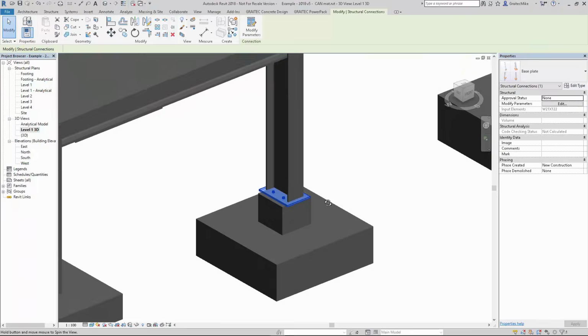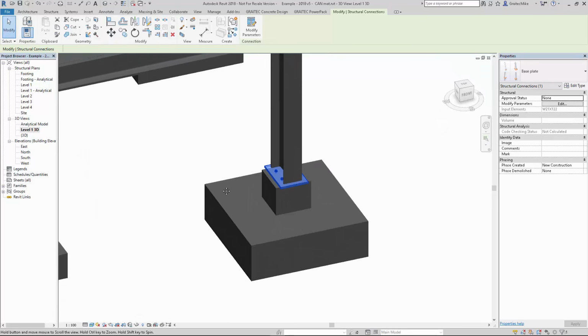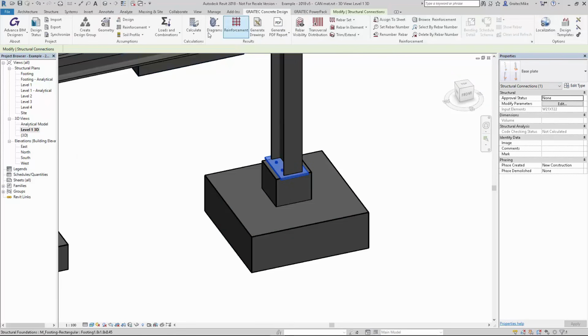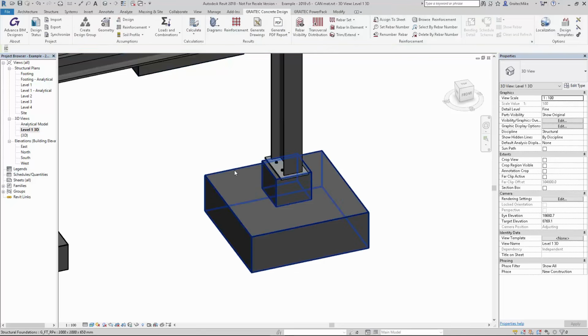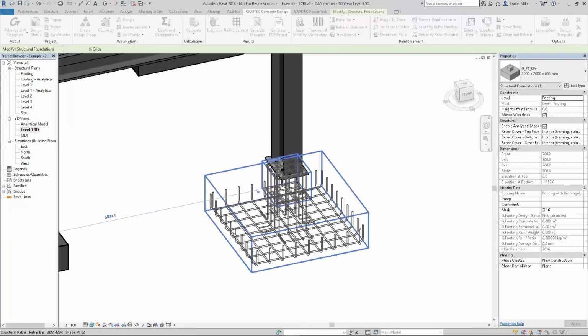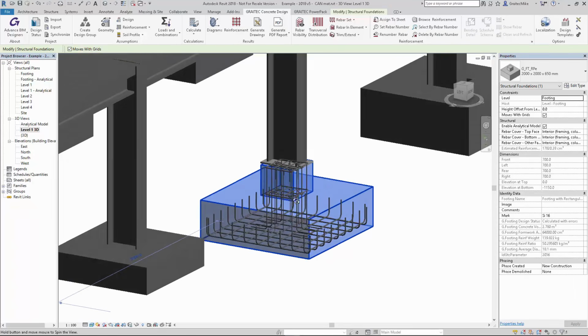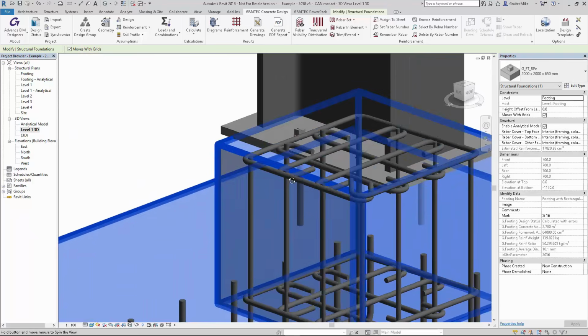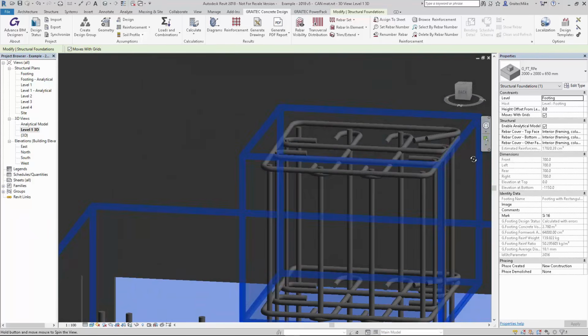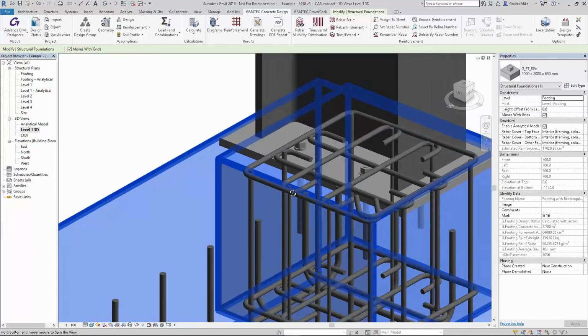Once we launch our calculation for our concrete element, we'll be able to see the rebar in 3D. This will give us a view and ensure we could verify if there is a conflict between several elements. So we're launching the calculation here. We're going to get the 3D rebar cage, and we're going to get the rebar in the pedestal as well. We could see those link rebars that are conflicting with the pedestal anchors.